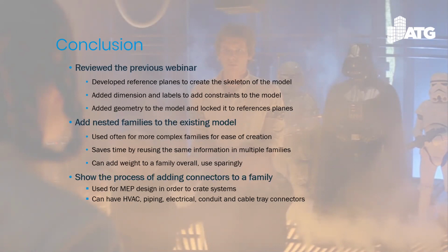And then lastly, in the last part of the session, I went through creating some connectors in a family for the MEP people that are on the call here. Obviously, we need to have connectors added into the families to create systems. They're a necessary item. We have each of the different types of connectors: HVAC connectors, ductwork, piping, electrical, conduit, and cable tray.